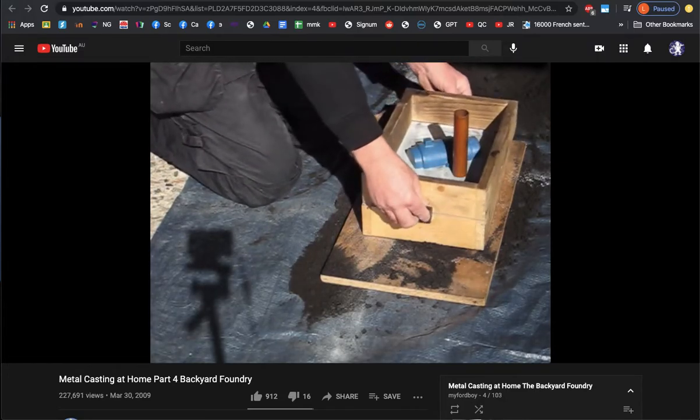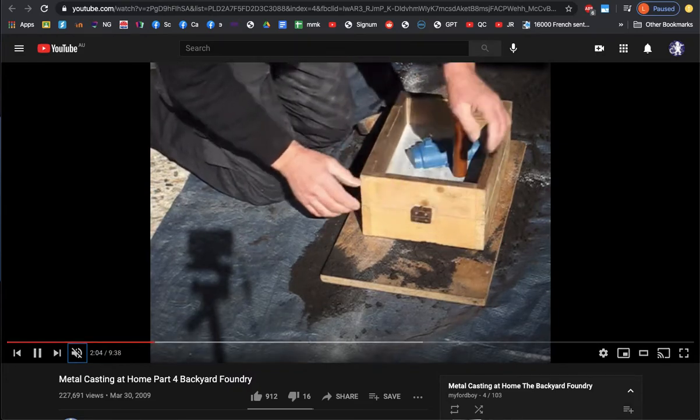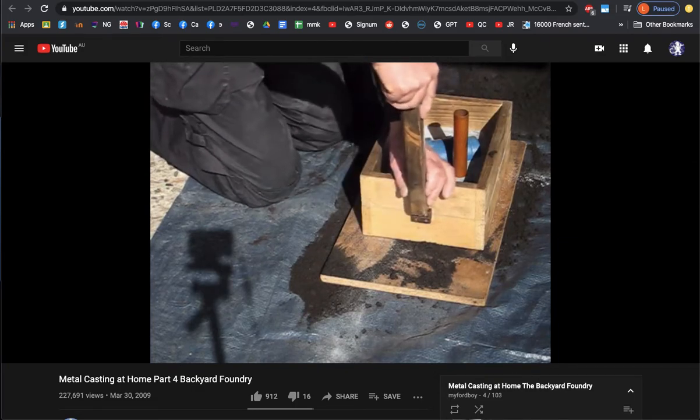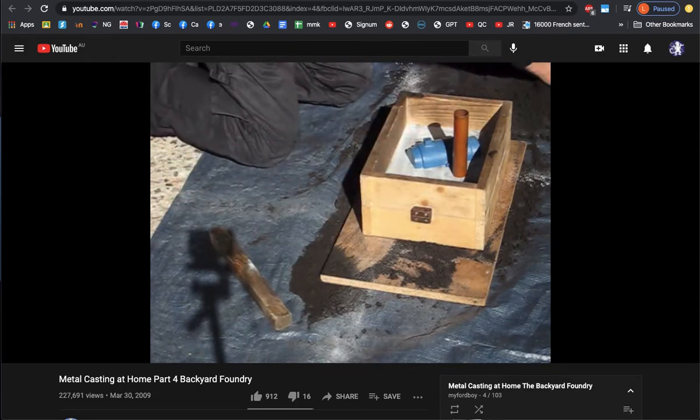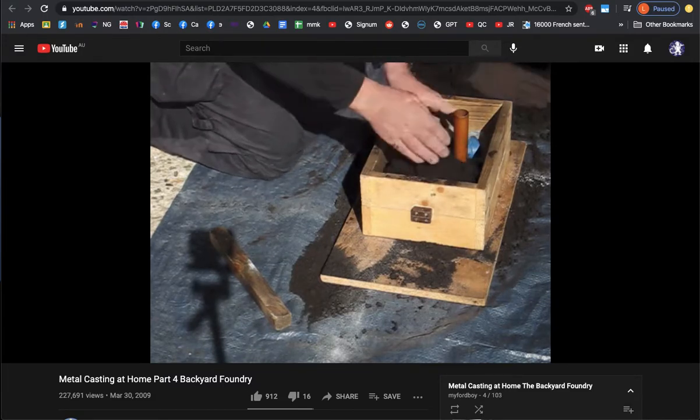Now, the question you might ask is, there are two parts of this mold, the cope and the drag. We're going to learn about that more in the textbook, but there's some terminology we use. We also have things like the runner and the riser. The runner is so that we can pour the metal into the mold, and then the riser is for the overflow. We usually want to add about 25% more metal than we think we need, so that it gets into all the voids. There are locking pins that hold the box together so that it doesn't move around, so that we don't have our shape being warped.